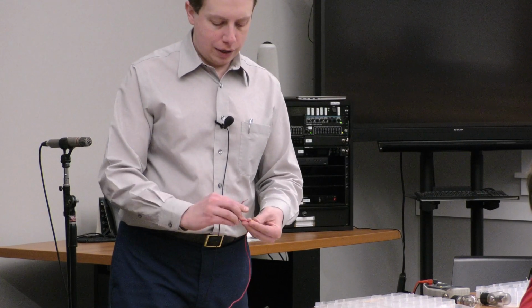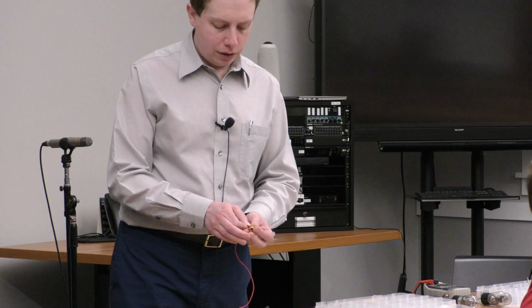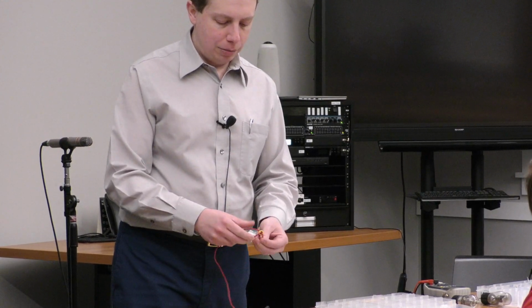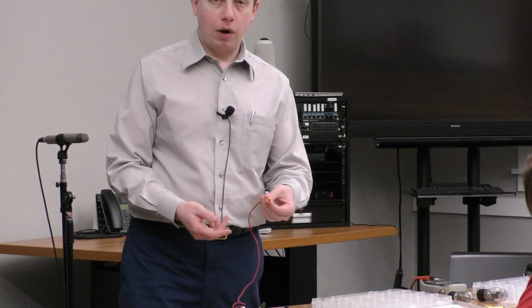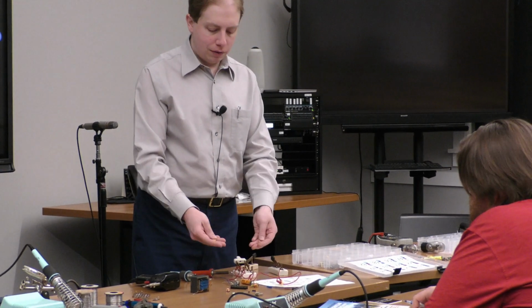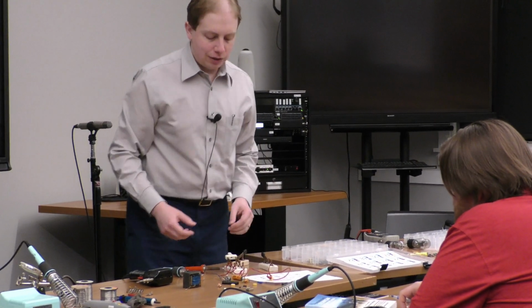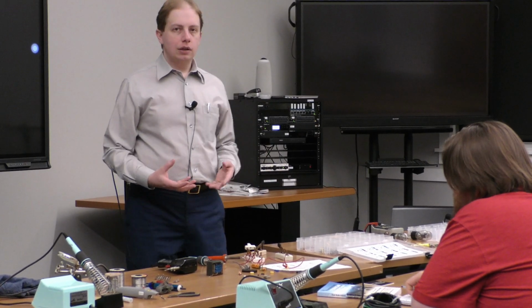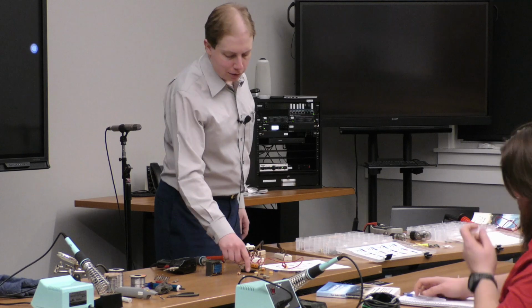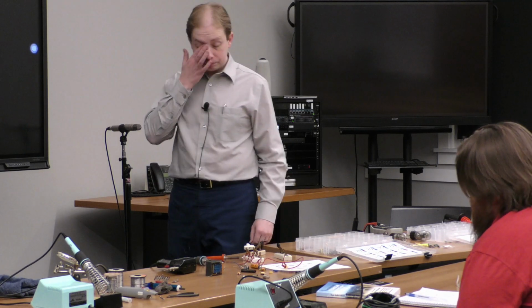So it's not unusual to wind your own ferrite inductor, because you might need a very particular inductance for a tuned circuit, and you literally wind it with wire. I've got a whole cabinet full of these. These come in different values too. The values are based on the size, but also the mix of that iron powder in the ferrite. So it's pretty common to use those and build your own.